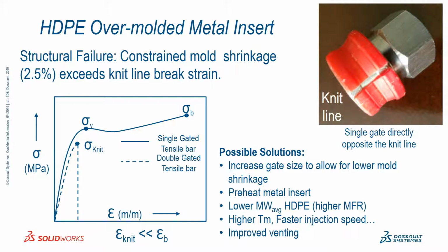And when we think about weld strength, maybe we shouldn't think about strength. What we should really think about is strain. Welds can be strong. They could be 90% as strong as the material would be otherwise. But what a weld will not do generally is stretch a long distance before it breaks. So in this particular case, if we look at the stress strain curve, the strength of the weld is pretty good, but the breaking strain is very low.